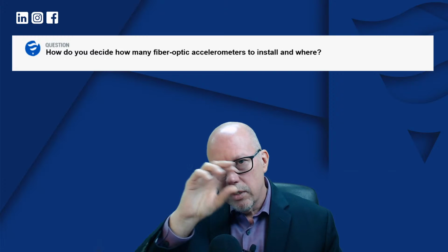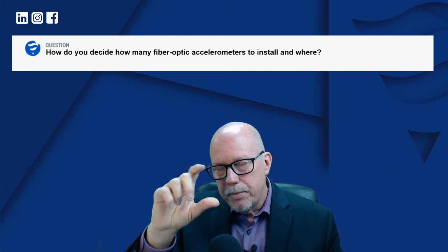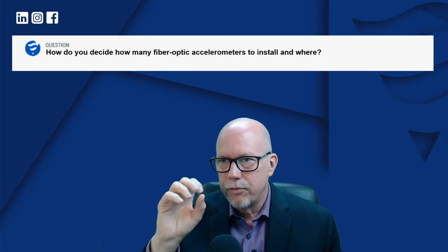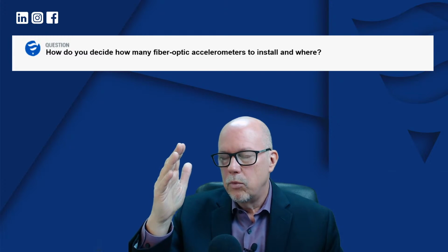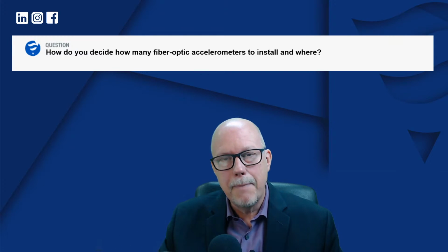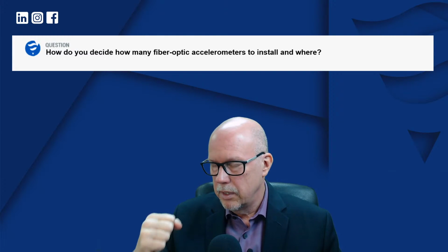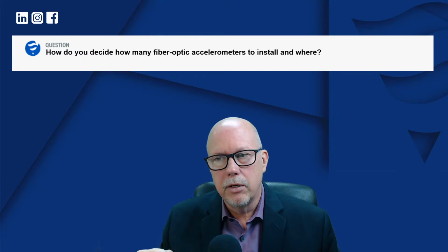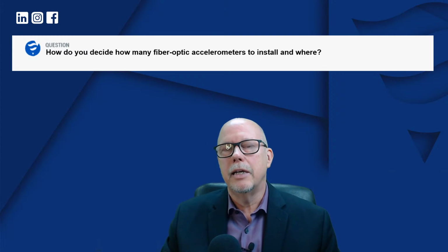You could see the 100 hertz signal, and you could see that there was periodic repeatable cases where the high frequency would show up on the signal, which for us represents a low frequency impact. Something is actually hitting on the end windings to make that appear. Now, of course, units in operation, nobody is standing next to the winding and hitting it.